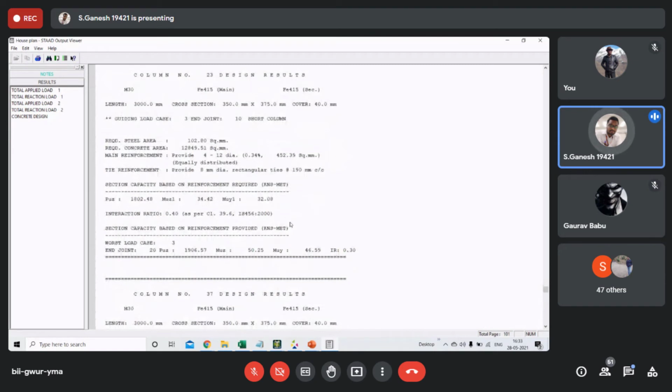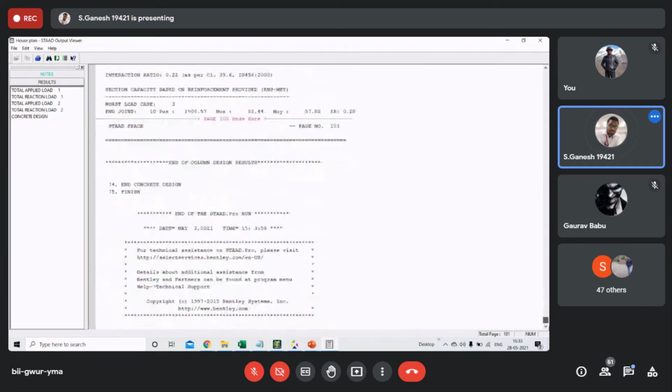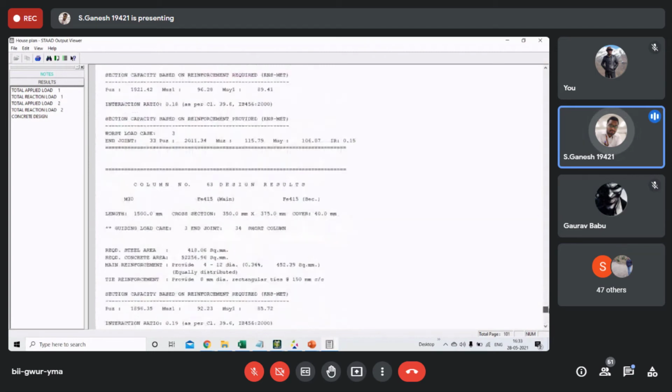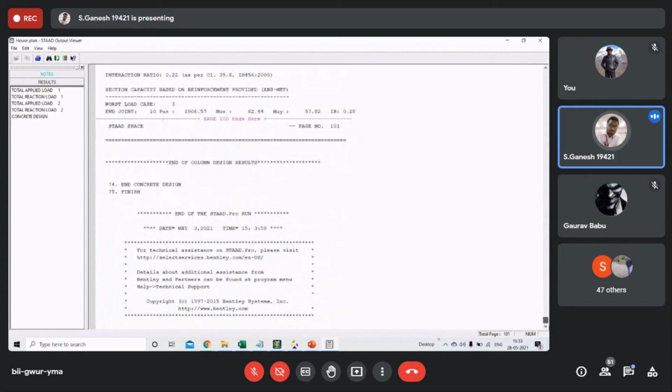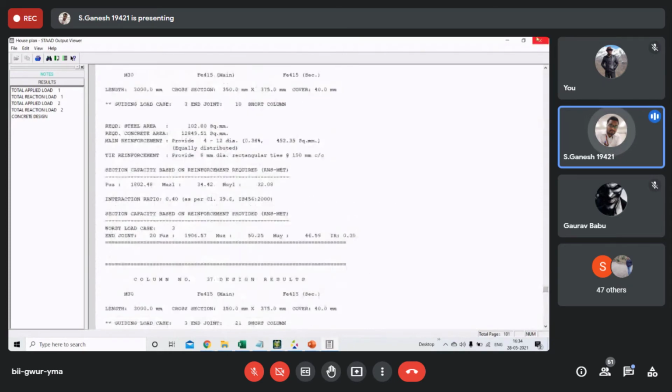As I said already, the slab design is not possible in STAAD Pro. For slab, we will take to Connect Edition. So slab detailing is possible in Connect Edition. You get full details of the slab, what the spacings are, everything you will be getting there. And finally, this is a takeoff. I have not given takeoff, I guess. Let me check. Yeah, here there is no takeoff command. Right. So going back to the design.